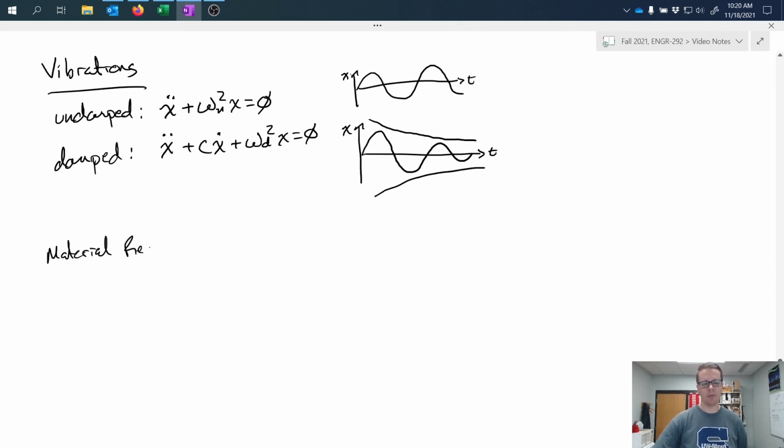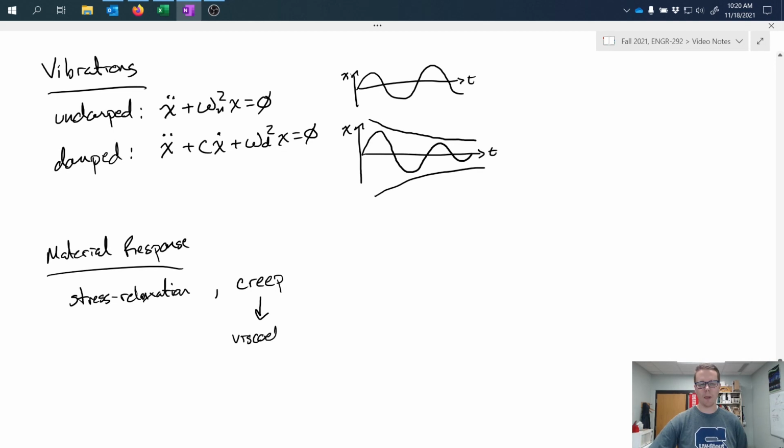We talked very briefly about material response to dynamic loads, and specifically looked at viscoelastic materials, where we have some unique properties. And we saw a couple of considerations that are interesting to look at: stress relaxation and creep, as different ways that viscoelastic materials may respond to dynamic input. We also saw that this principle of creep can give us an understanding of viscoelastic phase lag. So if a viscoelastic material represents basically a spring and a damper together, then we would expect it to behave like a damped system. So seeing that output and those results is useful for furthering our understanding of engineering principles and engineering